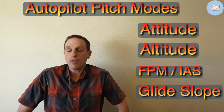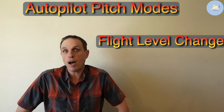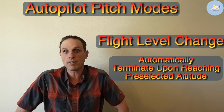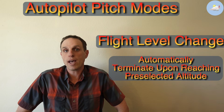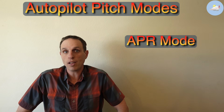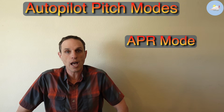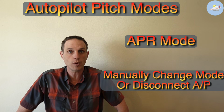And the really important thing to remember is that flight level changes can automatically terminate upon reaching the altitude that you set in the altitude pre-select box. When you have the autopilot following a glide slope, however, it will follow that glide slope indefinitely. It will never automatically switch out of following a glide slope until you manually switch one of these pitch control modes. Now, the autopilot stays on that glide slope indefinitely for good reason.